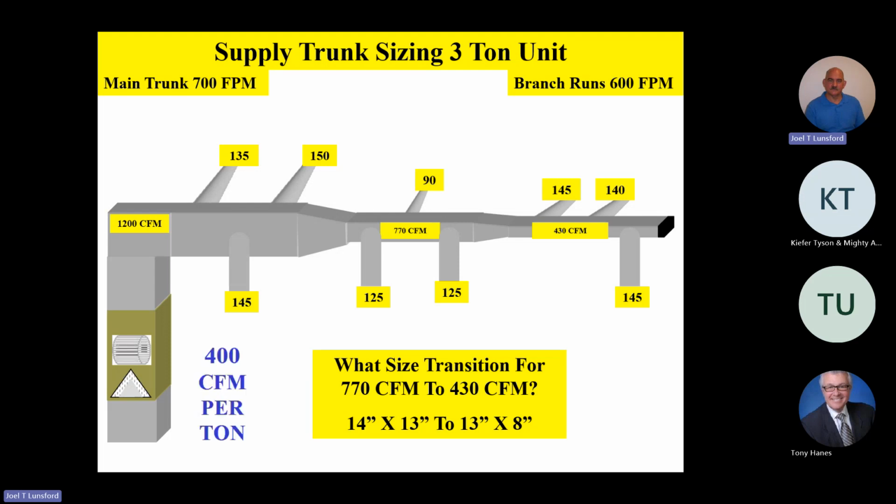As a matter of fact, as long as it was sealed up nice and the ductwork was well insulated, you'd be able to deliver 95% of that system's capacity into the space where it belongs. And by the way, the number one reason systems do not perform properly is airflow. And so airflow is the most important thing that you can do on an install.